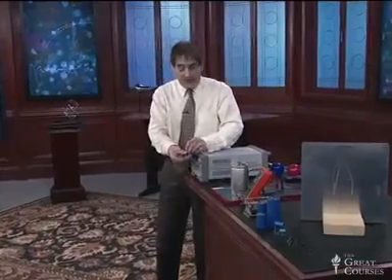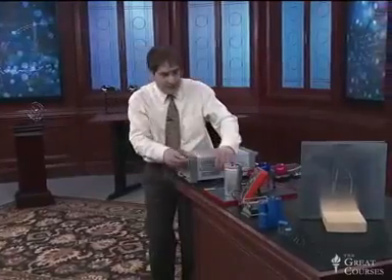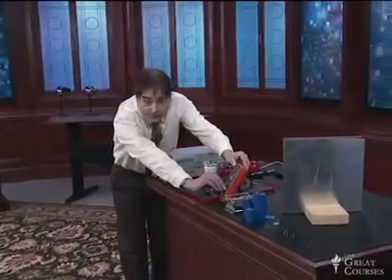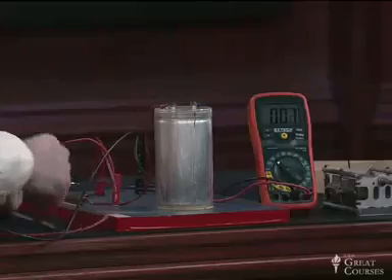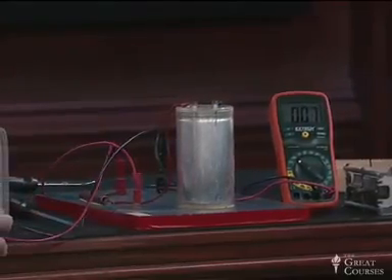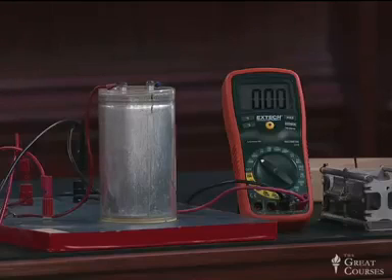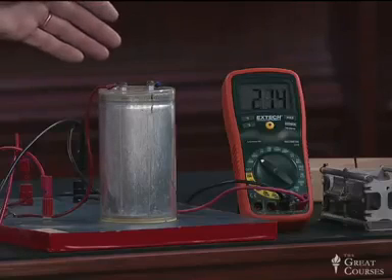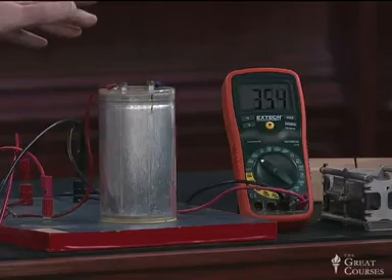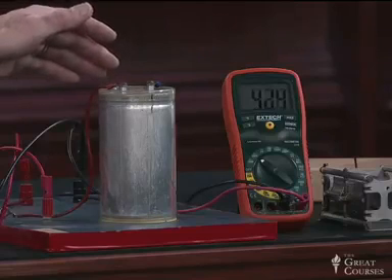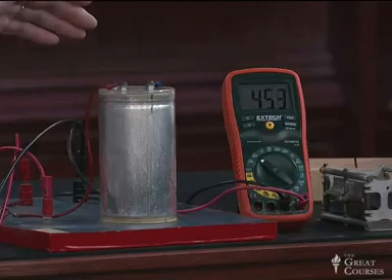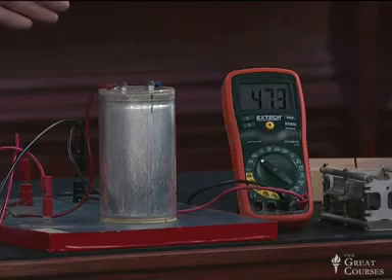Okay, so I'm going to connect my capacitor to this power supply. First, I'll turn on my voltmeter so I can record the voltage across the capacitor. It will actually take a little while for it to build up. I'm going to apply a voltage here, and we're going to watch that voltage build up gradually. I'll show you later why it's happening gradually. There it is. We're at 30, 40 volts, 43, 45, 46. There we go, building up, and reaching about 50 volts, which is about the maximum it's going to get to because of the settings on my power supply.